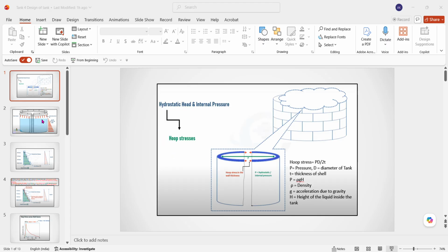Here we have ignored the joint efficiency and eliminated the corrosion allowance. Whatever design thickness you calculate should be less than the thickness calculated by the 1 foot method, and whatever thickness we get for the hydrostatic test method should also be less than the thickness governed by the 1 foot method. And this is the thickness of the second course.